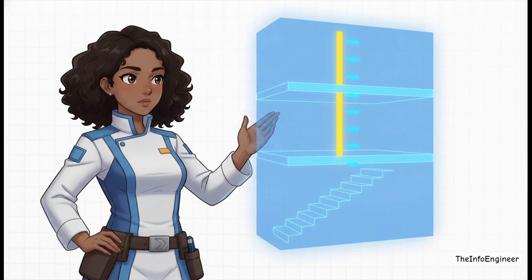If the math spits out a fraction, you always round up to the next whole number, which slightly lowers the actual riser height to a safe, compliant level. And once you have that final number of risers, everything else just cascades from there. It unlocks the minimum required going, which then dictates the total length of the staircase footprint, which directly determines the ultimate volume of your bill of quantities.